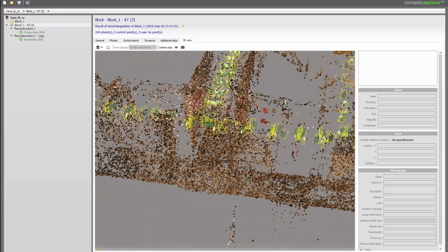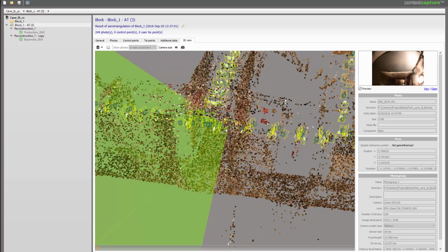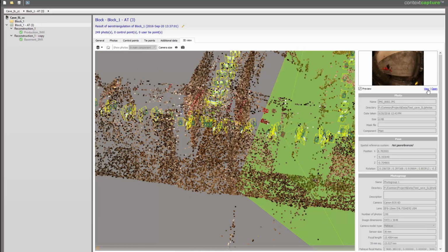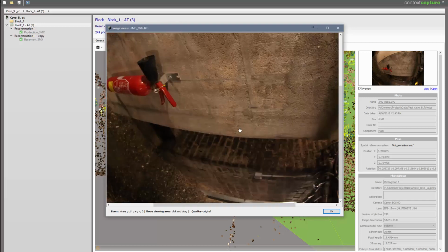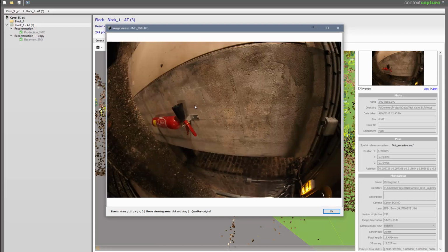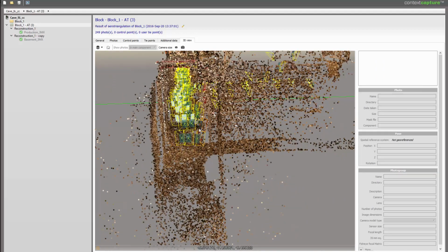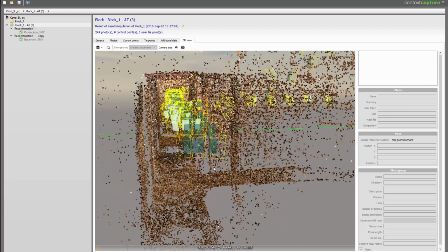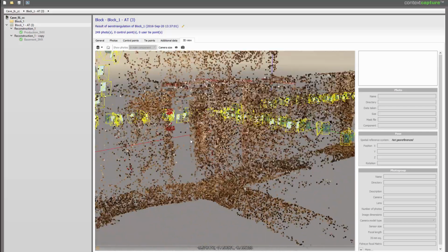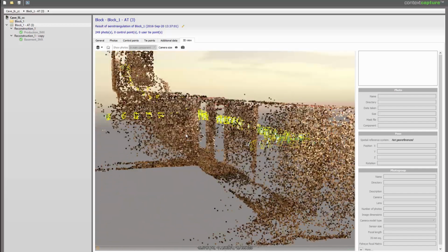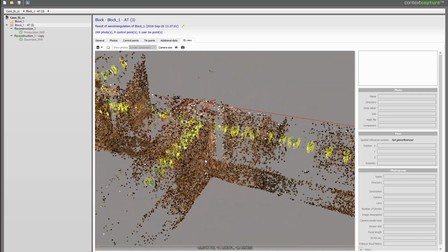I managed to get it to work well by using a fisheye lens to circumvent the fact that the environment is really narrow. And I used a DSLR camera with a good ISO range to be able to work under low lighting conditions. I worked by taking a round of photos every, let's say, 60 to 80 centimeters, so basically at each step.